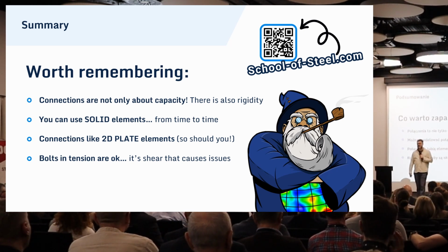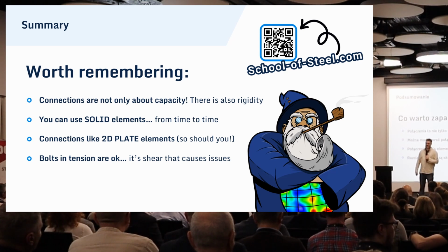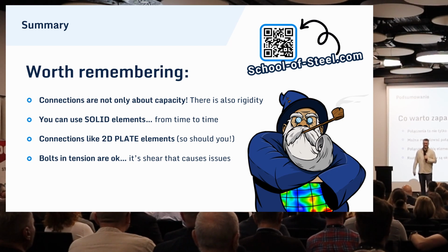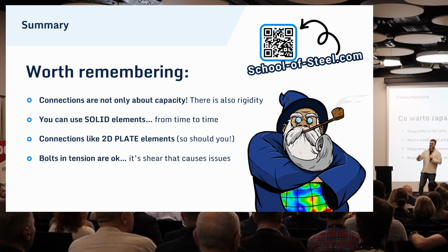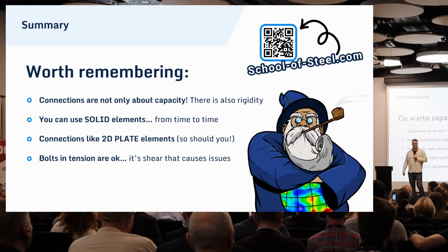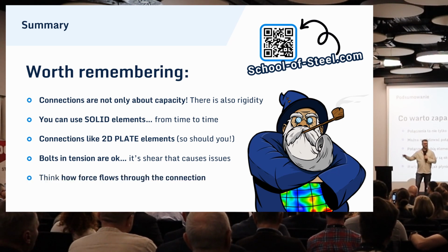The shear connection, if you have to calculate bolts in shear and you really care about shear distribution in a plate because you're in a situation that this stress will add up to some other stresses in your model, then you will simply have to model it this way. I admit that the advanced model of bolt modeling is difficult and time-consuming, but it's better than nothing, because at least it allows you to solve the problem that you may have.